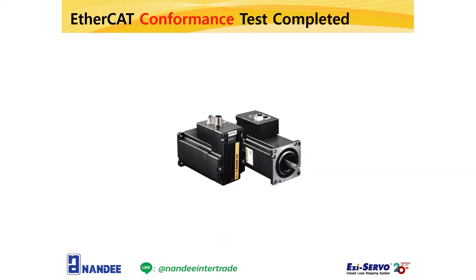As you checked before, although FASTECH EtherCAT product has completed the compatibility verification and received the official certification, it doesn't prove the compatibility with each manufacturer's EtherCAT master. Thus, in cooperation with FASTECH and the major EtherCAT master companies, compatibility verification between master and slave based on CIA402, a standard profile for EtherCAT drive motion control, has been completed, which is a distinctive feature of FASTECH EtherCAT products.